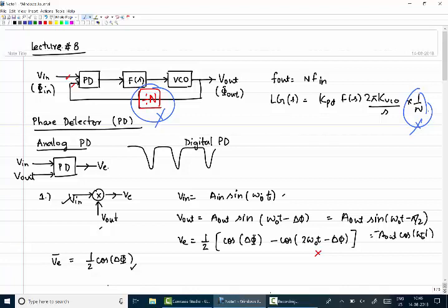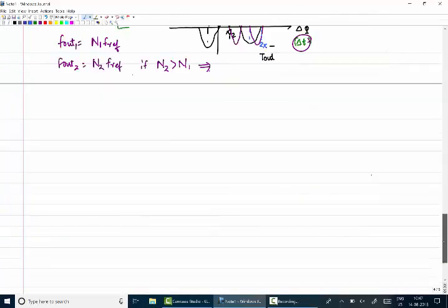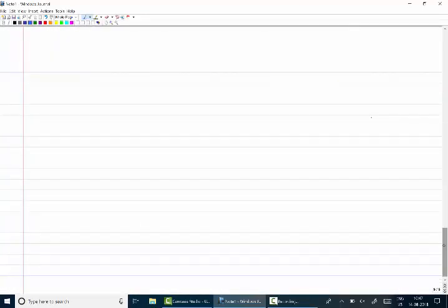So that is not what we can say is faster. Faster depends a lot on the bandwidth of the PLL itself. The only difference which I want to point out right now is that by using a subsample based phase detector, the big difference is no divider in the feedback loop. That's it. So these are the two different analog based phase error detectors.